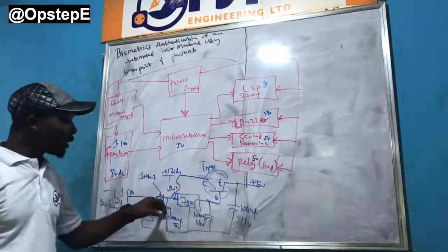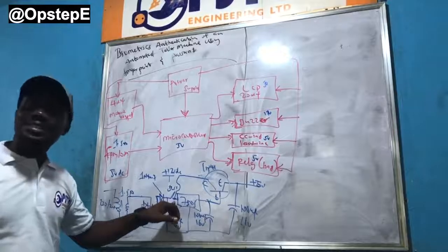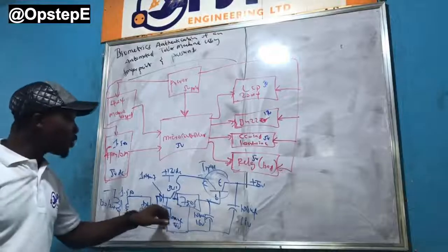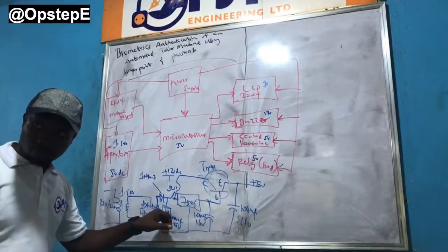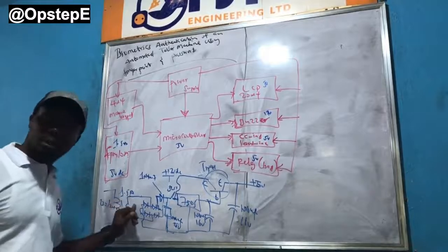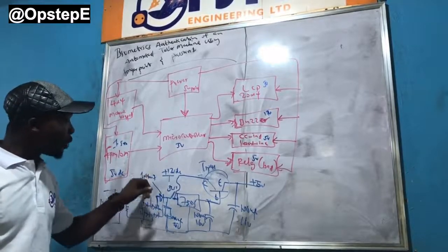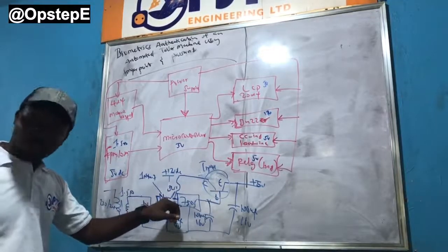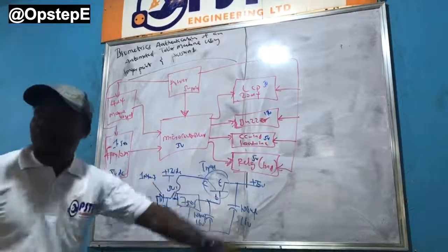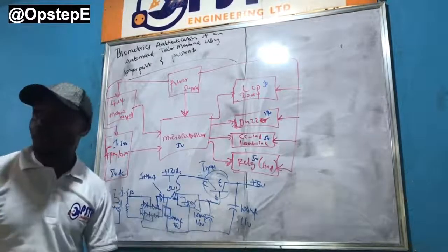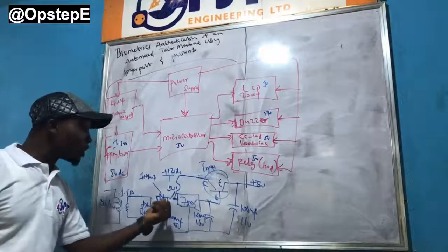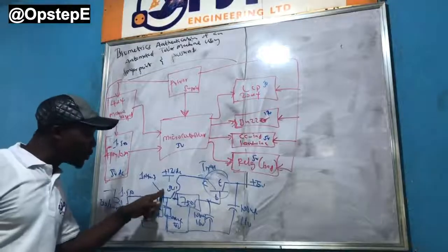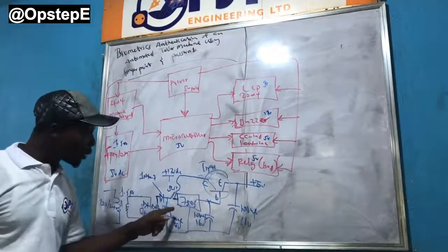The collector must be connected to an input source that has an infinite amount of current to supply. What that means is this: if the battery was not here, and it was only this transformer you were using, and you already have a diode there, 1N4007, even though you have placed this transistor here, it is still not going to produce more than 1 amp, even though it can deliver up to 10 amps to you. Why? Because the source itself cannot actually produce more than 1 amp. Not because it only has 1 amp, but because this diode is there to only allow 1 amp to get in.